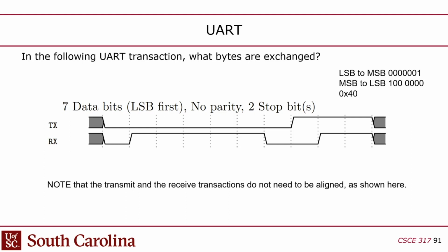Okay, so when you have the parity bit, you have the potential of a parity error. That's when the receiver counts the number of 1 bits, and it's not what's expected, right? So if you have even parity, you expect the number of 1 bits to be even. But if the receiver sees that's not the case, then it knows there must be an error. That error could be caused by noise, but most likely it's caused by synchronization. It's because of metastability. It's because there's no clock, right? That's usually what the errors are caused by.